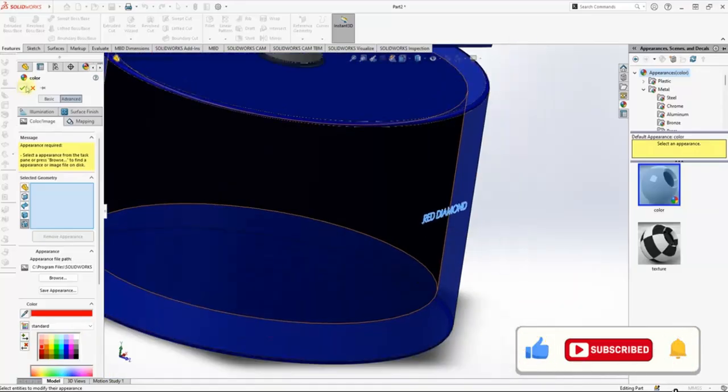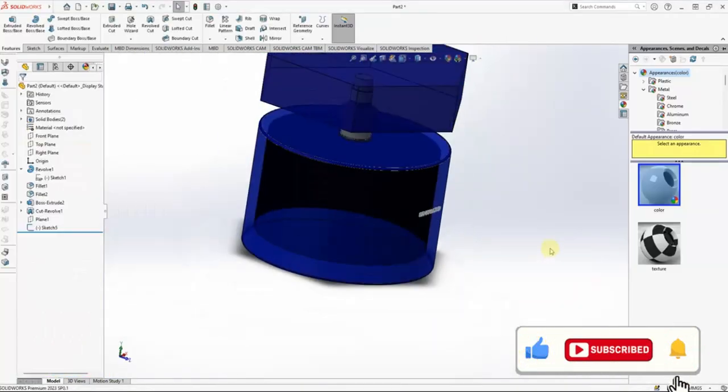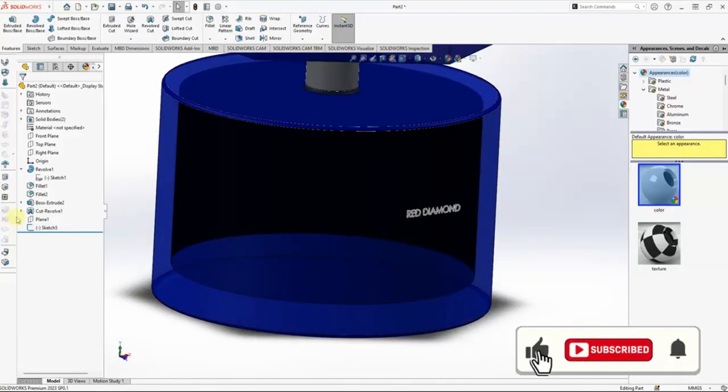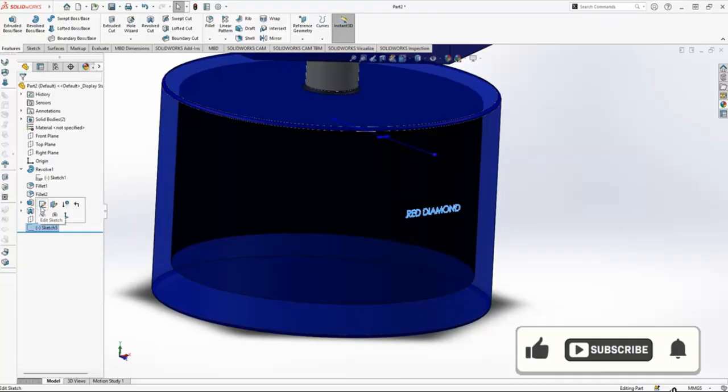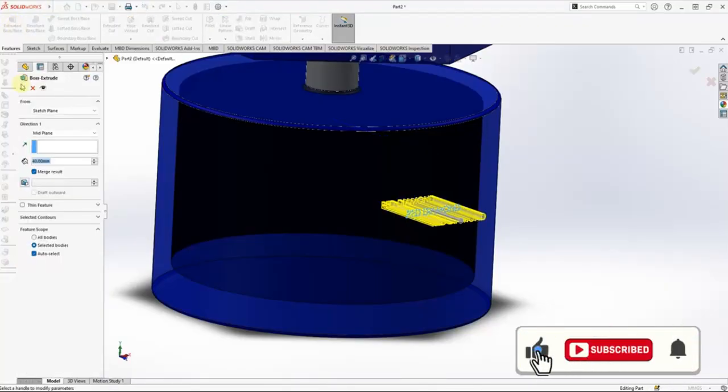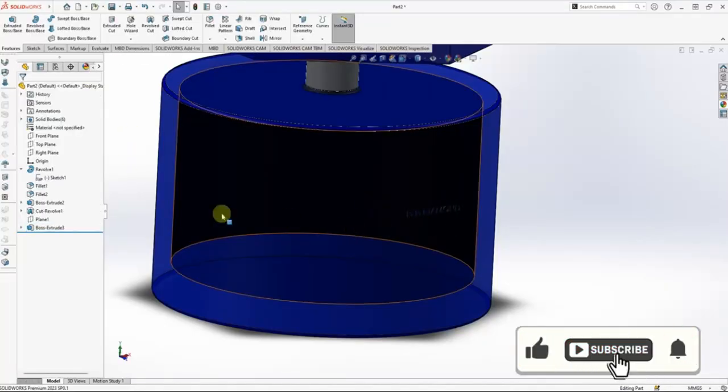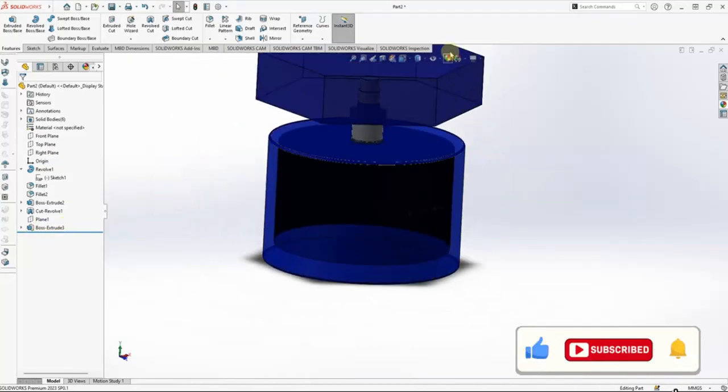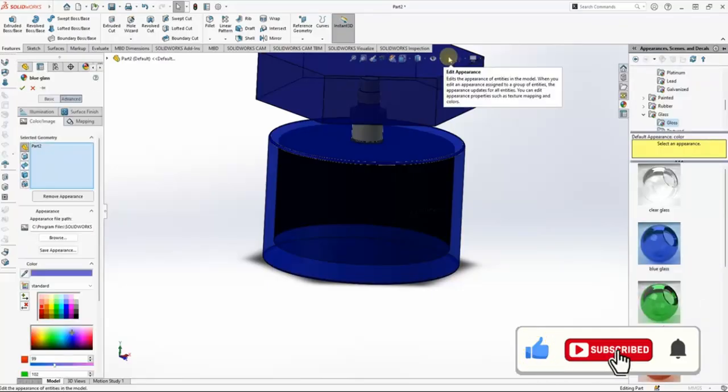Select geometry. Okay. Now, I made a mistake. I've now actually extruded it. Now this sketch surface, click on edit sketch. Okay, let's come right here to extrude boss base. Should have extruded it by a distance of, let's say, 1 millimeter, or let's say 1.5 millimeters. Sorry, that was our mistake. Now come right here to boss extrude. You can now edit.